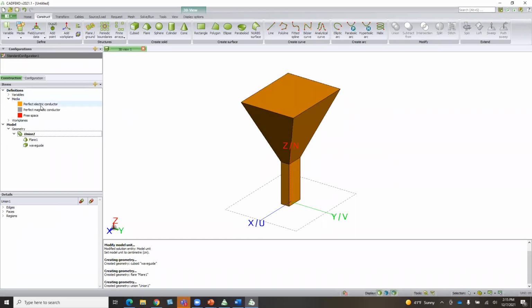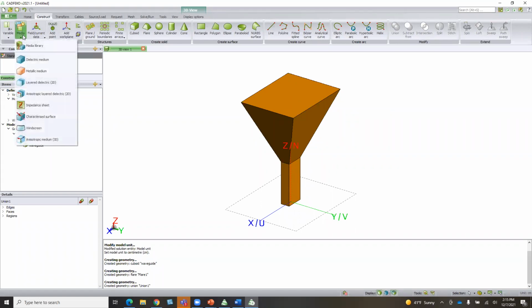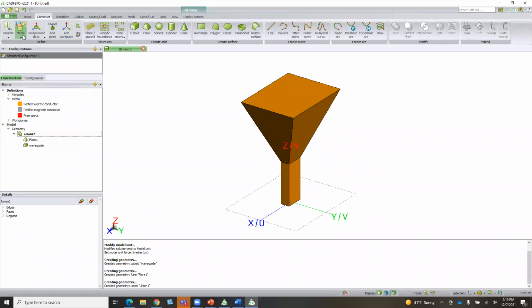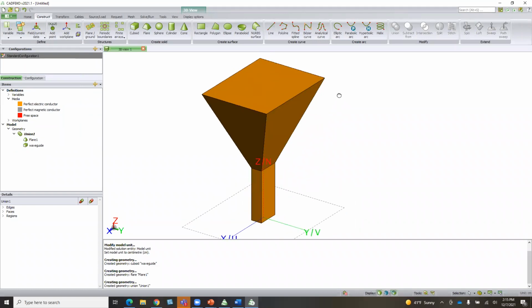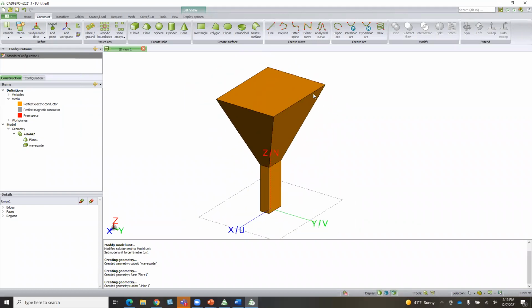And when you see when it happens, the default parameters specify the value as an electric conductor. You can also change the media type for non-antenna applications. Maybe you're looking at EMC applications where you need to change to a metallic medium or dielectric medium. You can specify those criteria there. But I'm going to keep the default properties. One thing you'll notice here is we need to have this open, representing what we expect with an actual antenna. So we need to open this up.